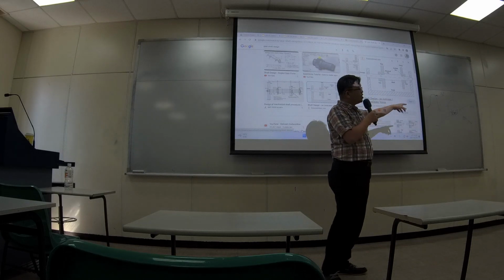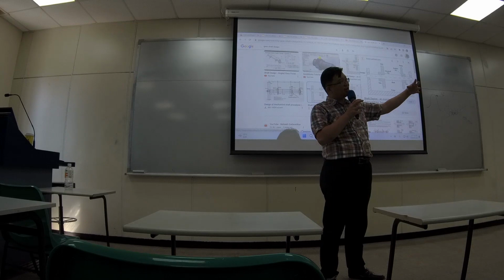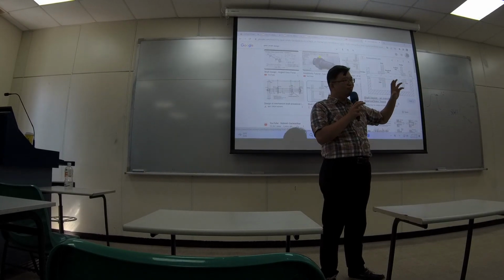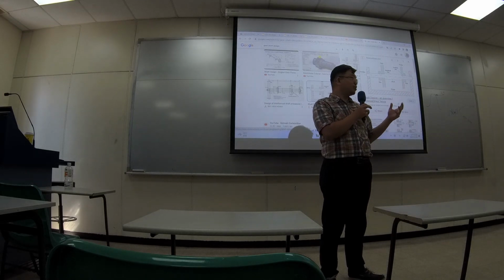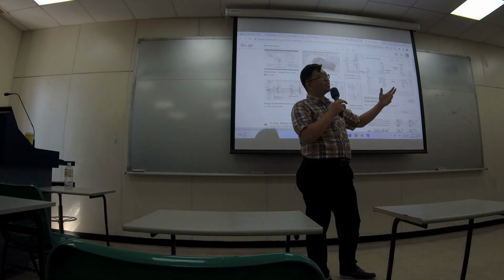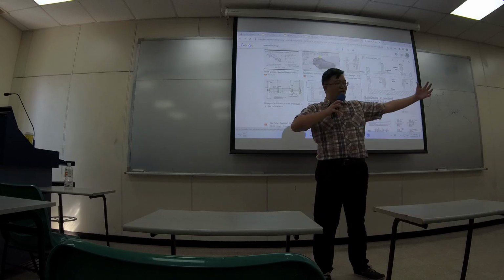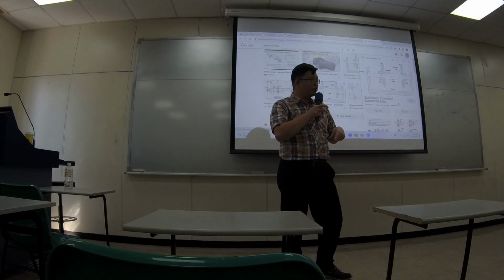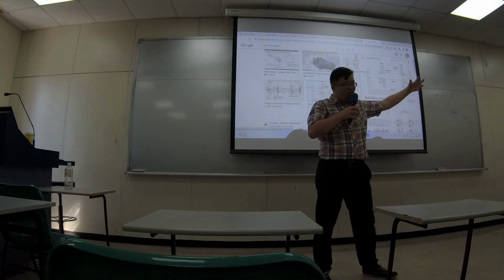If you use a pulley, it's based on a belt. It's a flexible part, so there's room for deformation. If you use a pulley and belt, it's simpler because you can have a longer belt. Your driving axis could be here, your driven one could be far away, and you use a belt to hook them up.